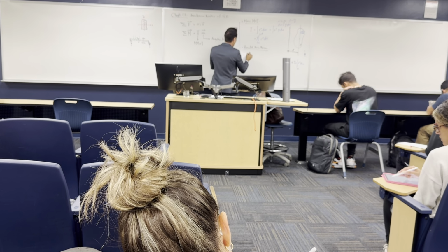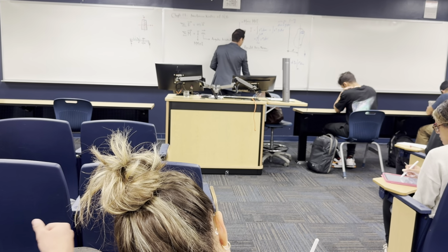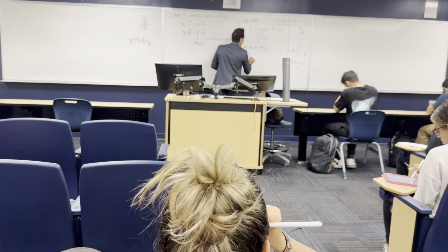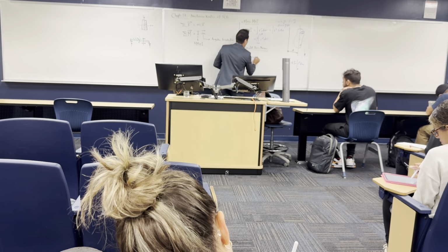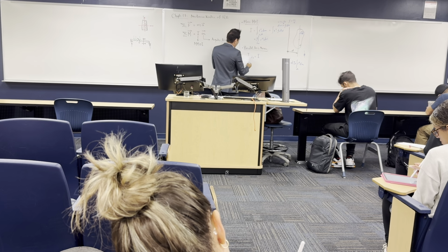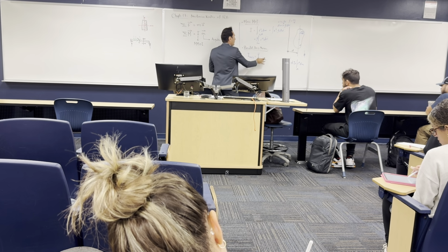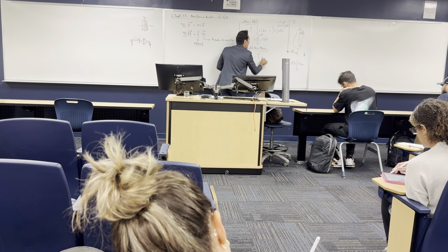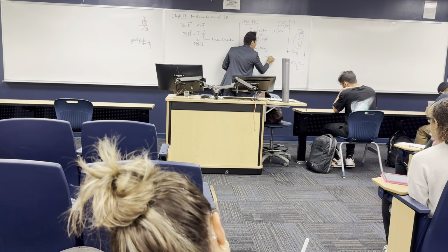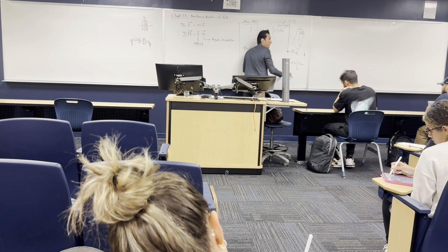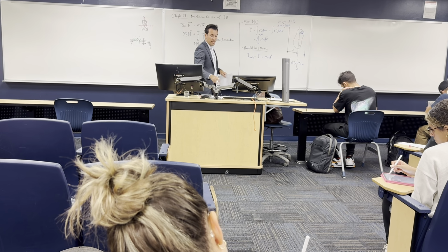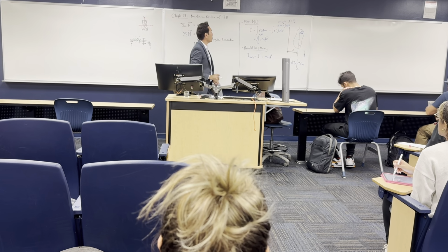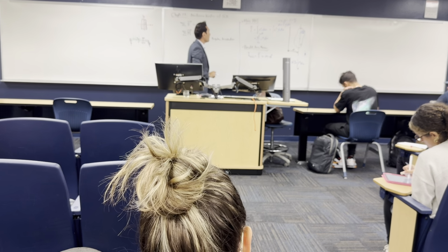So it says that the I about any axis is equal to I bar, the moment of inertia of the body about the CG, plus the mass of the entire body multiplied by the distance d squared, this distance. That's what's called the parallel axis theorem, and I proved it in my notes, so if you want to look at the proof, you can double check it.